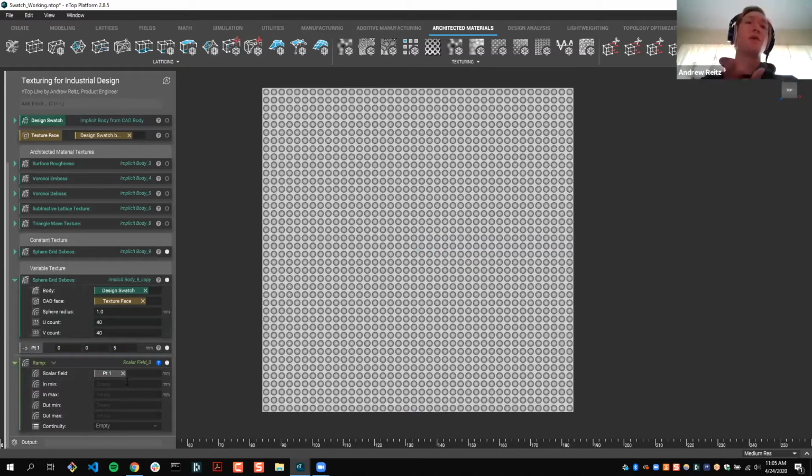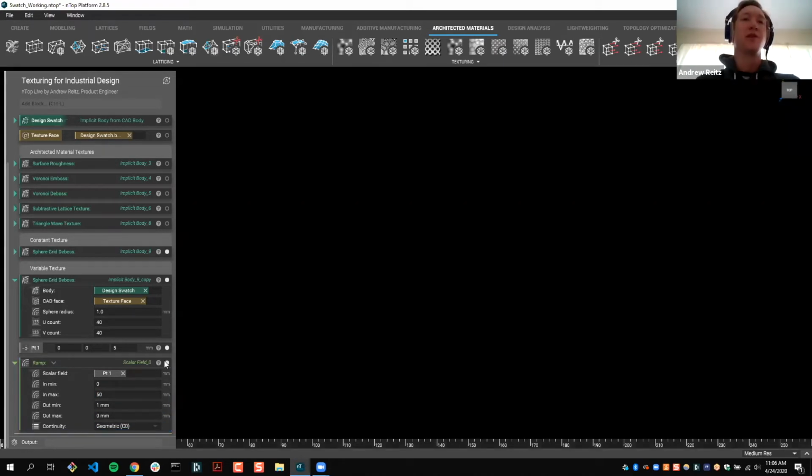And then what I want to do is to say, okay, if you're on top of this point, or if you're near this point, so 0 millimeter, I want the sphere radius to be 1 millimeter. And then I'm going to go back here and say, as you move away, and I know my swatch is about 100 millimeters, so let's say at 50, I want your radius value to be nothing. And then I'm just going to select the first option here, which is a linear fall off.